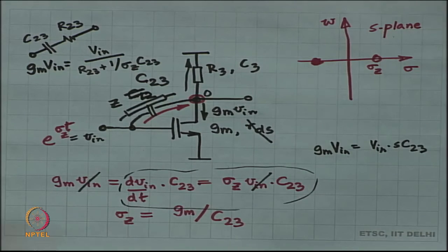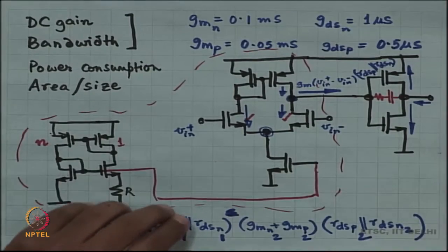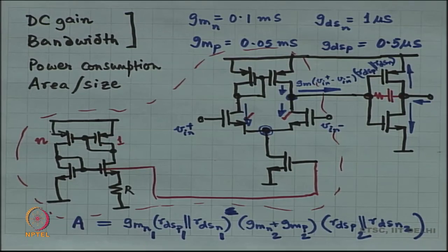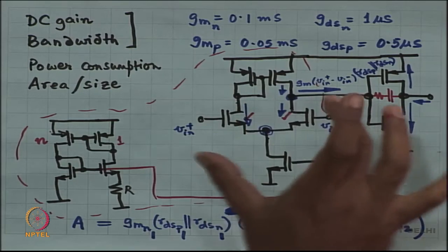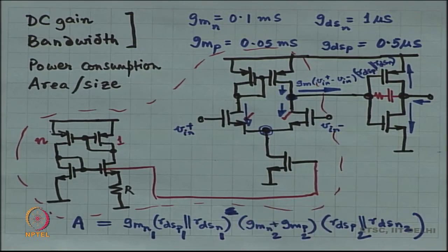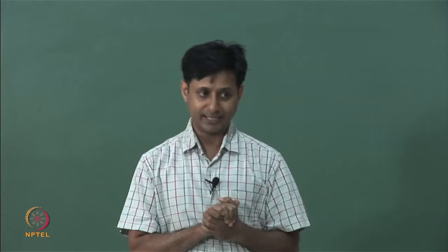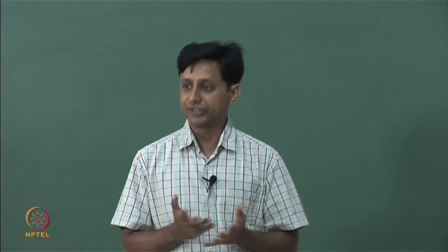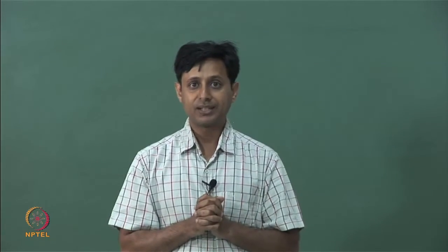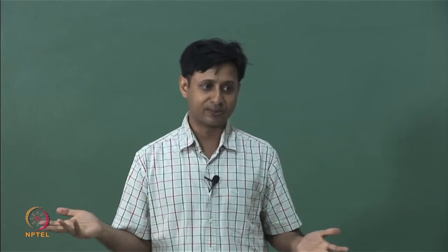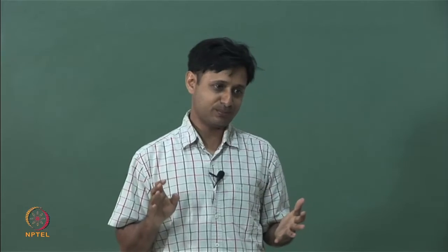We also figured out how our overall compensation technique is related to our op amp design, right. We took an example of a complicated one, this is actually not a simple example. This self biased active load op amp, diff amp, is actually one of the more complicated ones. If you think of an ordinary differential amplifier which is completely symmetric, then the result is even easier, because you just break it up into half circuits and in the half circuit you do the compensation, right.